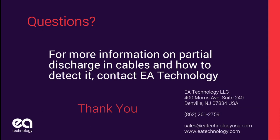We see about 25% of the time online that you get a big enough reflection to calculate the distance, because when you do an offline test, you lift both ends of the cable, you have a very abrupt change in impedance, and that's what causes a reflection. When you're online, you have less of a difference in impedance, so you get a smaller reflection, plus you have a higher noise floor. So we see 25% or so of the PD we detect, you can actually determine the distance, but that's not the real goal.